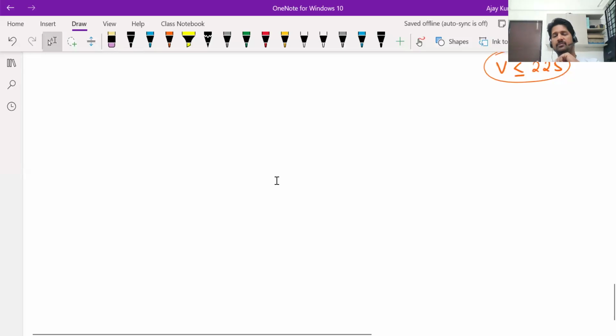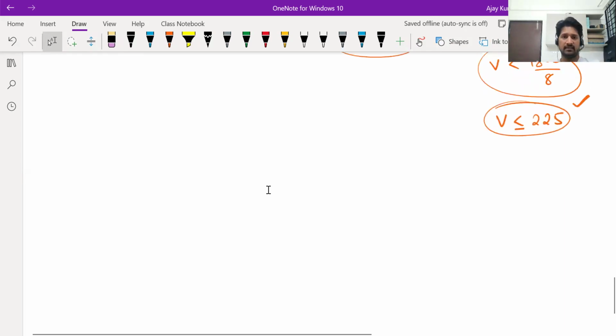And because dielectric is being placed inside a capacitor, the capacitor will also have a rated voltage. It will have a maximum voltage that it can bear. If you supply more voltage than that, the dielectric between the plates of a capacitor becomes a conductor and the charges on the plates of the capacitor will combine. It will give out a spark. The positive and negative charge combine, it gives out a spark, which in most cases damages the capacitor. Okay, so we should ensure that the capacitors don't get voltage more than the rated voltage. Okay, so let's try one question like that.